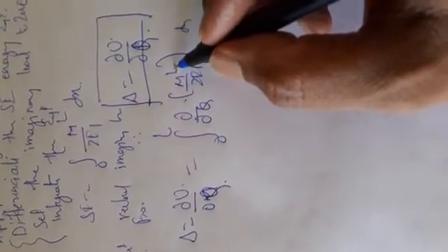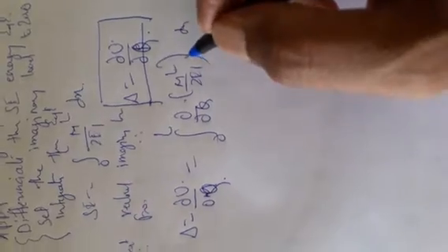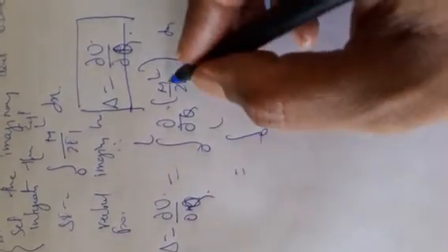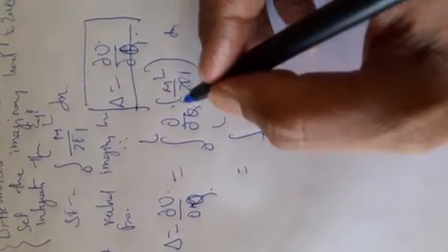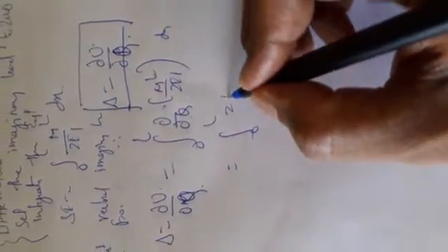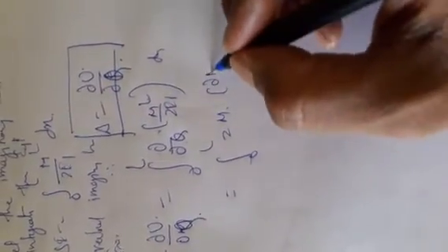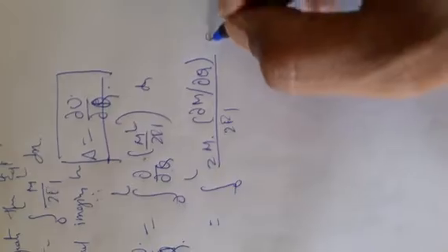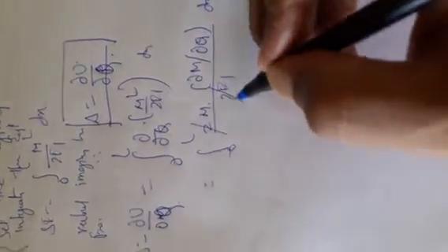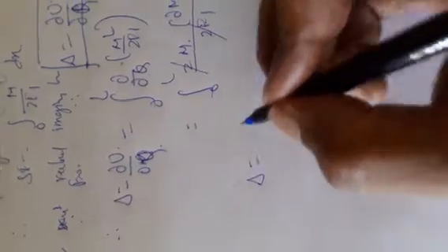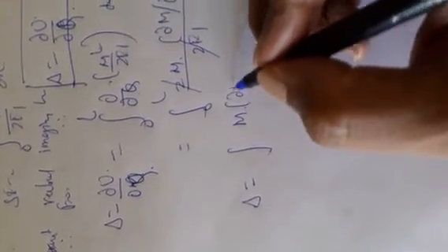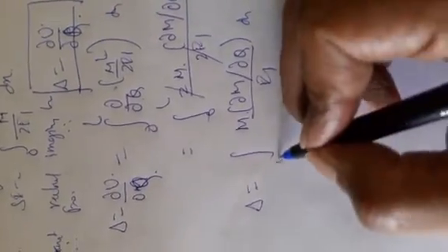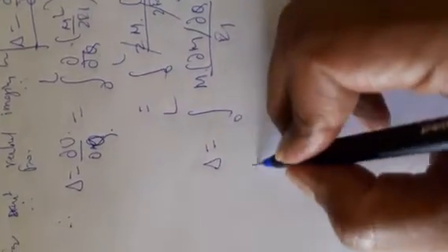So this we have to differentiate with respect to Q, and this I am having as integral 0 to L of partial differentiation of M square, which is 2M dou M by dou Q, with respect to 2 EI dx. These get cancelled, so I am left with delta is equal to integral 0 to L of M dou M by dou Q by EI dx.